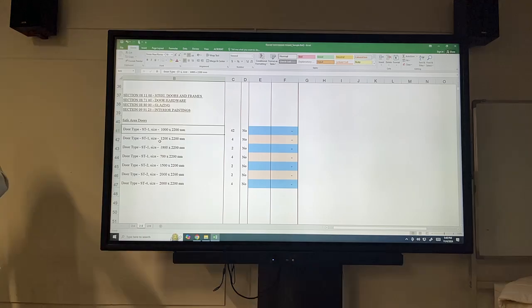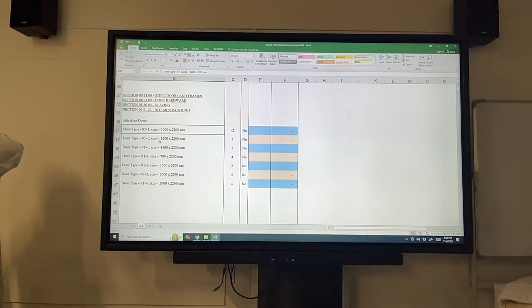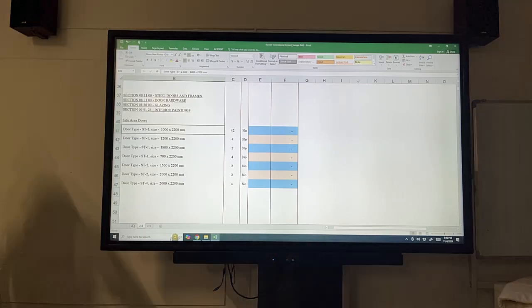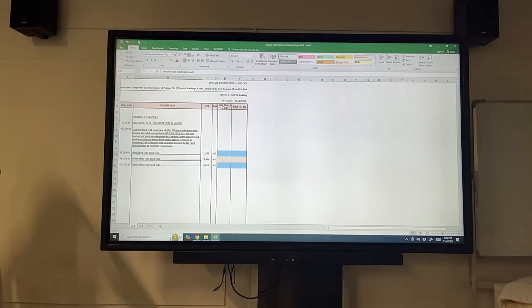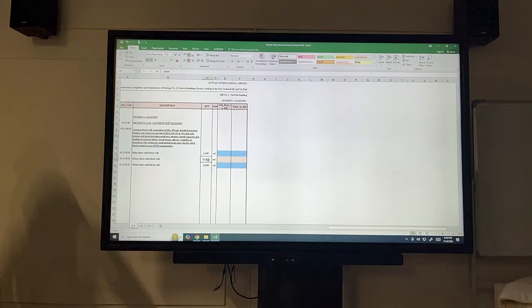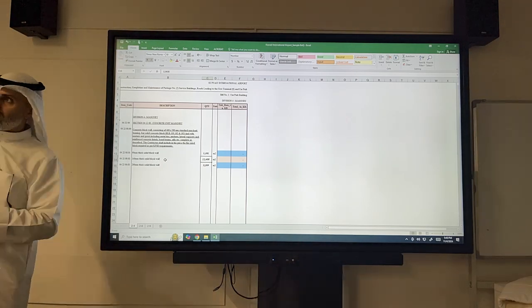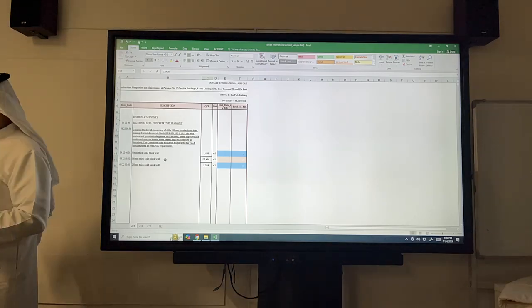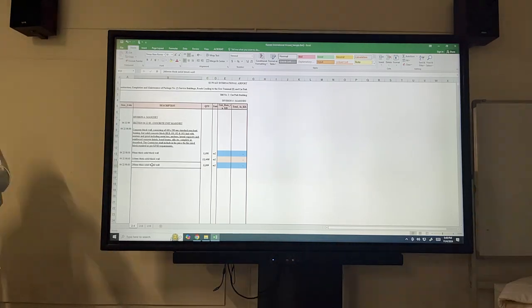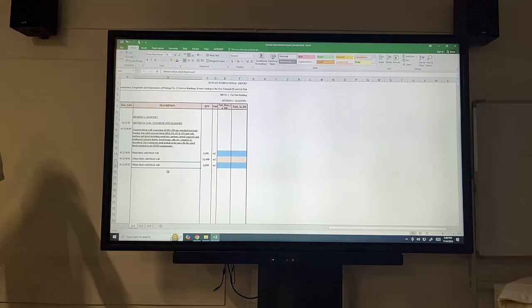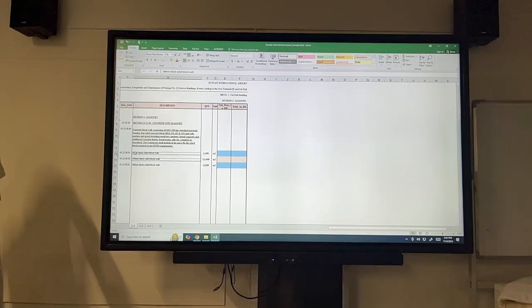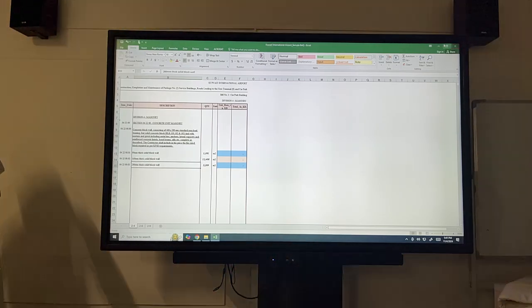And some basic ones, and again, these will be in detailed descriptions in the specifications. And here, I'll show you an example. This is about masonry. Solid block, CMU. It tells us in square meters, and then you have 12,000 meters of CMU that will be built. That's, for example, 10 meters, and that's the total area for the project. So the contractor can then calculate how much it will cost per square meter for that. You have 90, you have 140, 200, different standards used. So that's an example of a BOQ.